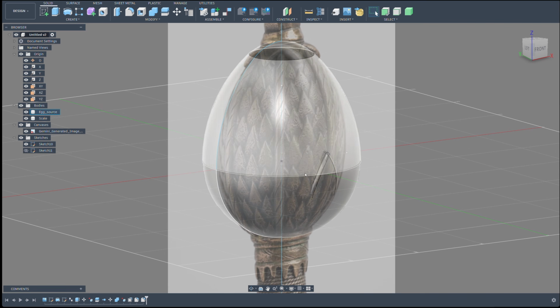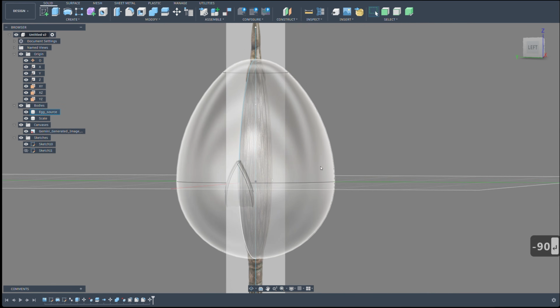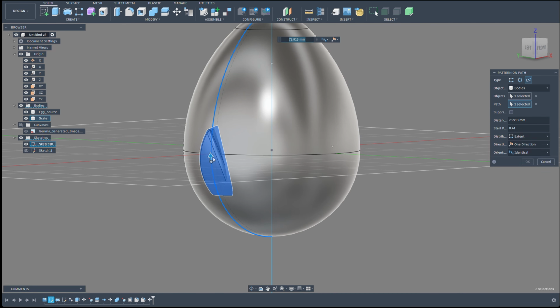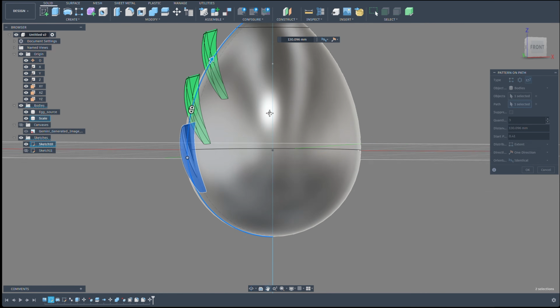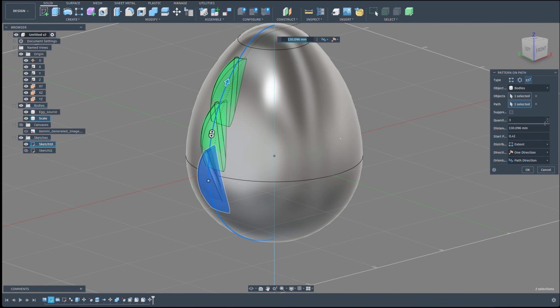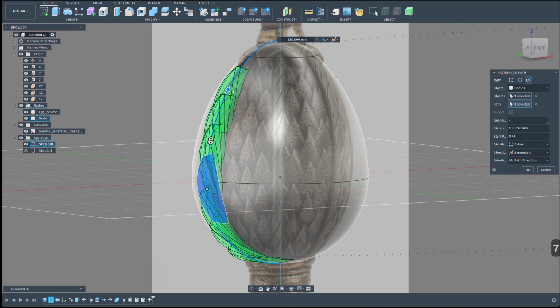Phase 3. Patterning and detailing. Let us rotate the scale element closer to the original egg profile line. We will pattern it along this line, taking the normal into account, symmetrically in both directions. On the reference, we have 7 fragments. Let us pull up the upper boundary.